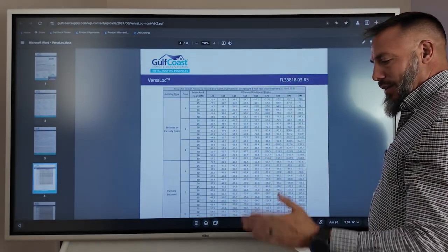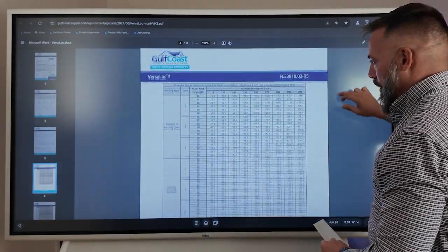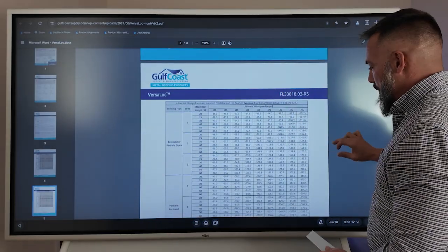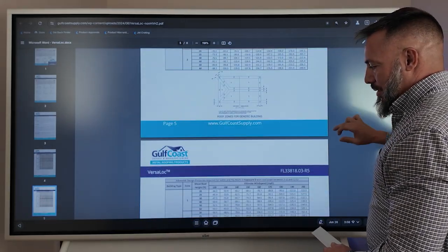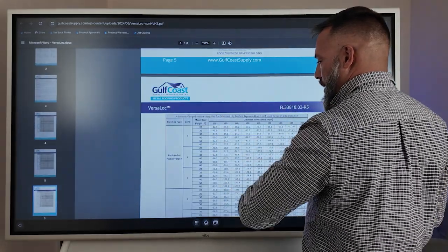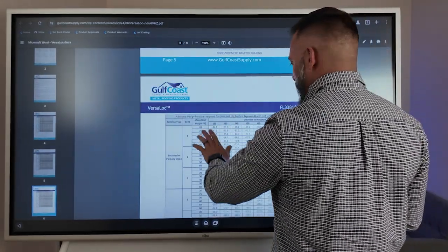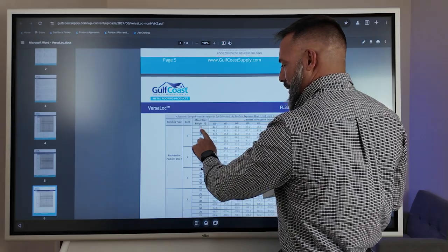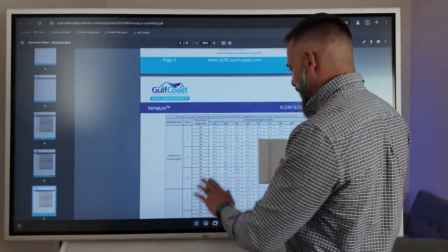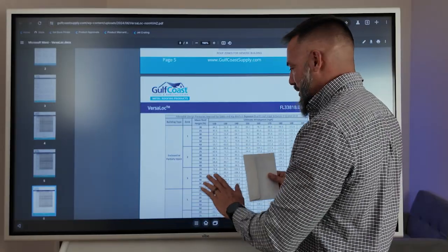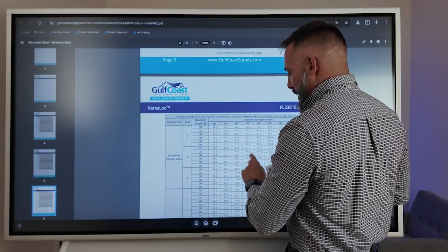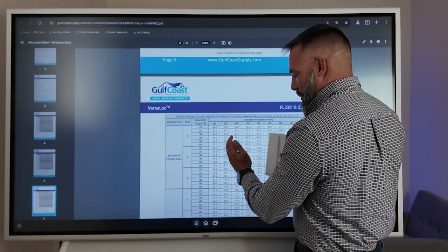So the only parts of this chart that I'm looking at are 140, 150, 160, and then exposure may change. If you're inland, it'll be your exposure B. If you're a little closer to the coast, exposure C, and then obviously right on the coast, I'll use my exposure D chart. So you may have to highlight 3 of these, but the majority of the time you're only dealing with a 20 or 25 foot roof height. I'm only dealing with exposure B the majority of the time. And when I only sell in a certain area, I'm only dealing with a couple of these wind speeds. So it really narrows down what you have to look at.